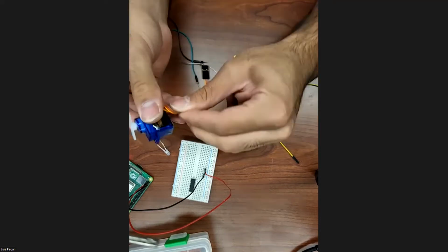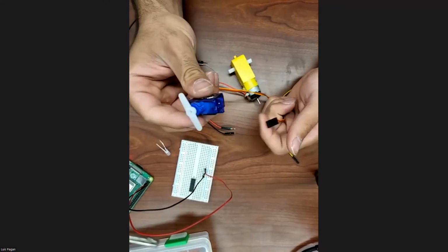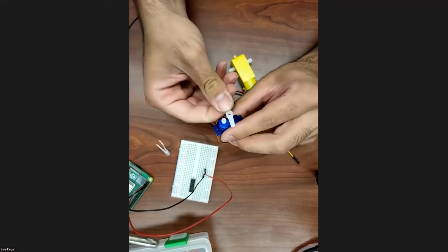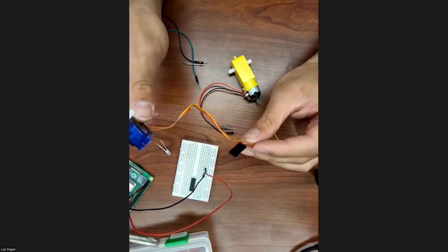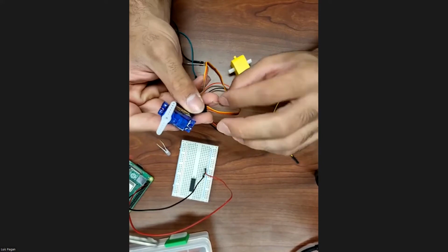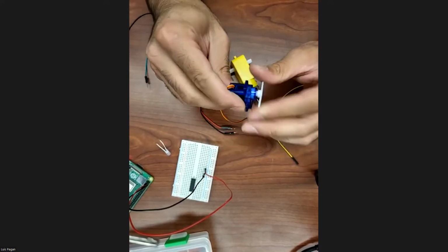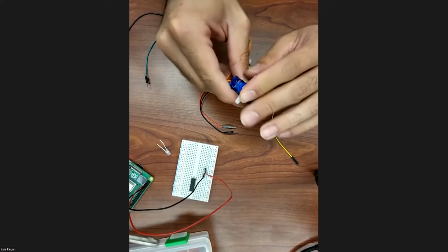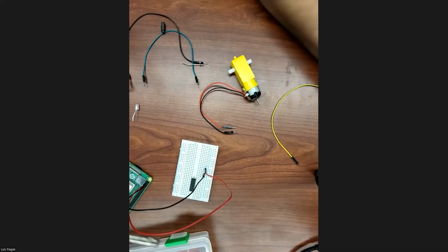So yeah, this is a different servo. They're really similar. I think this attachment works for this blue one and maybe not the other one, so I want to use this also. Brown is ground, red is power VCC, and orange is signal. So same thing, and you just got to apply a specific pulse signal to control the rotation.